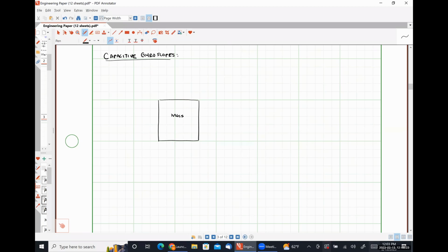We want to induce sinusoidal movement. Is there any particular reason why we could use a comb drive and lateral displacement? So that is exactly what we're going to use, because comb drives give us an easily controllable lateral displacement. We're going to put a comb drive on both sides so that we can cause it to move back and forth. We just have to make sure that our actuation is timed correctly so that our forces are pulling in the right direction. So you're nailing it, Steve.